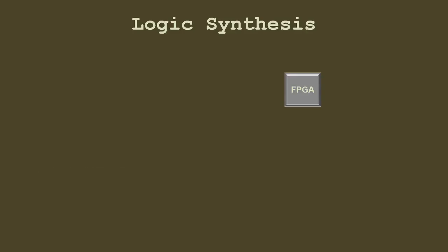In this video, we'll be discussing the process of synthesis. We have discussed how to simulate Verilog designs, and synthesis is the step after that. We basically want to test out our logic on FPGA, and doing that is called synthesis. We have a design available that we have verified in simulation, and we're confident that it will be running, but it has to be transferred onto an FPGA.